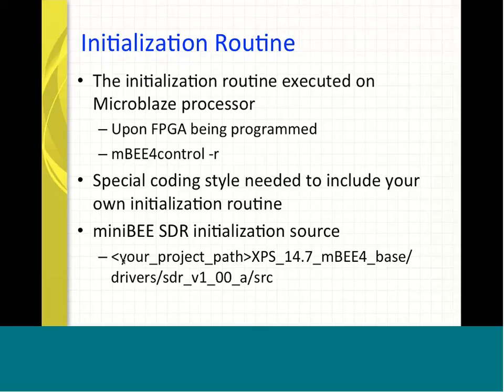If you want to implement a hardware reset, for example, you have some registers or some FIFOs that need to be reset, our recommendation is to implement a software register with, for example, one of the bits as the reset bit.